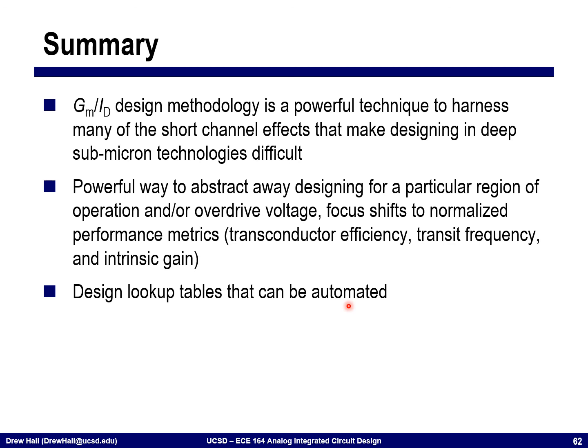And so oftentimes what I've done in the past is I will have a script that designs, for example, a folded cascode amplifier given a technology file, as well as a handful of different specs. And so this is literally just me running MATLAB that pops out all of the W's and all of the L's for all of the different transistors in the circuit. And then when I go simulate it, it's almost always spot on because I've used the technology that's been characterized with these lookup tables.